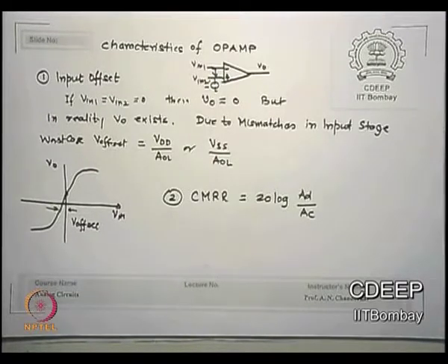All that we do is put a resistive network with a power supply, keep varying that pot, so that the output goes to 0. Is that correct? At V plus you put a divider and change the voltage or change the resistance, okay. See that when V0 goes to 0, we say offset is cancelled, but in real life offset may be present. Okay. Of course, we will not look into this.